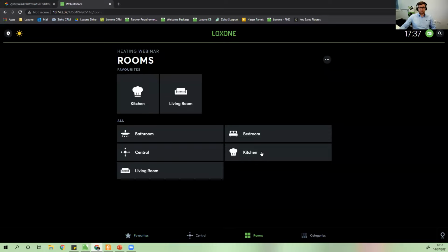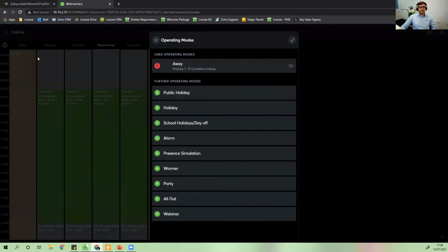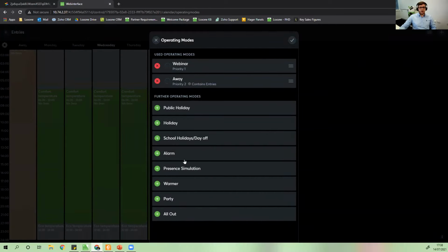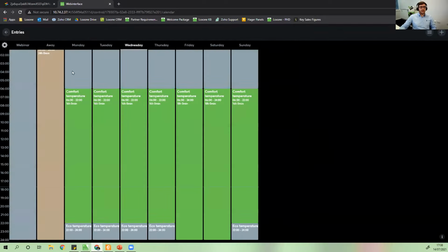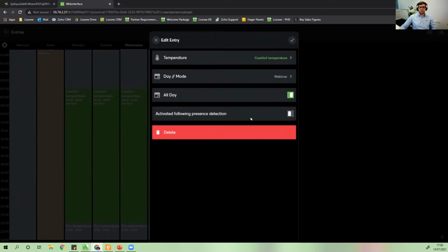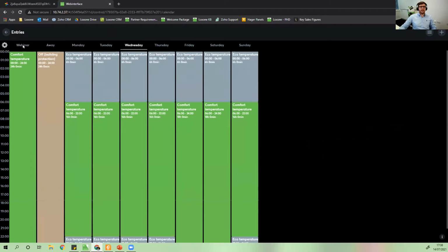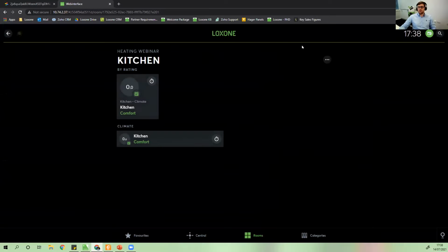So back to here, if we go to kitchen, for example, go to the schedule, I can go into here and add in that webinar operating mode that I've just created. And I can say that whenever a webinar is on, we want to be in comfort temperature all day long. Then anytime I say that I'm in webinar mode, we'll go to comfort 24/7. I could do that, for instance, through Automation Designer, but that is jumping onto another topic, so I won't go into too much detail.